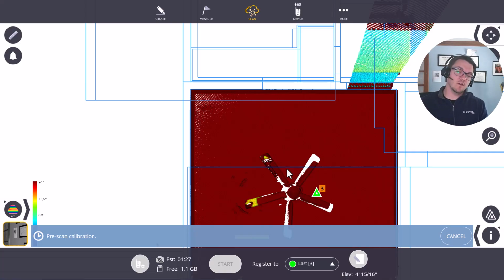We'll extract the target that's on the ground outside. And we're going to say the center of that target, I want to make not 0, not the center. I want to make the center 13 centimeters. I'm actually going to have to go out there and measure it again, but I'll show you the tilting target once we bring it in. But that'll allow me to adjust. So a couple scans in, if I want to adjust it, I always can, to make sure that what I'm calling zero, what I'm calling my reference elevation, whether it's 0 or 100, I can adjust for it.